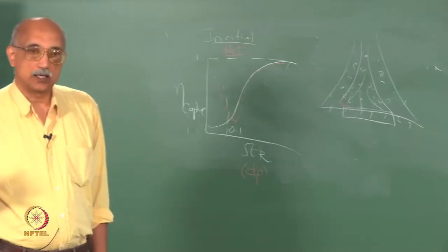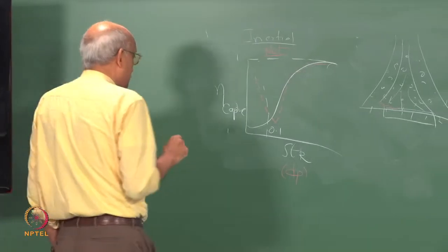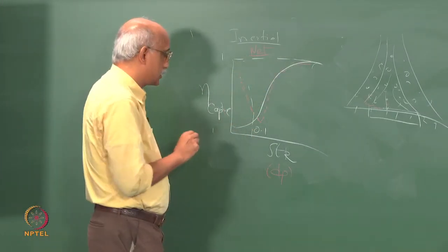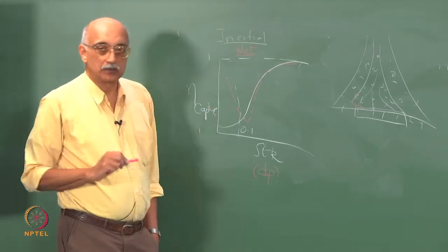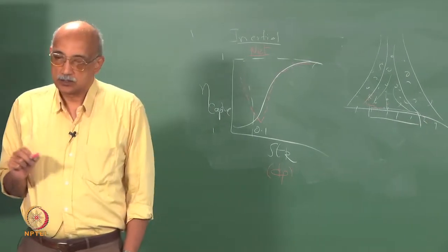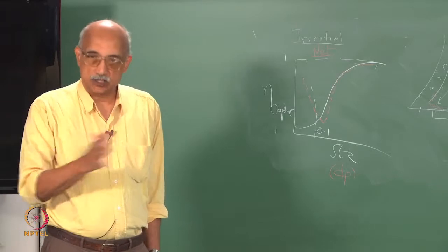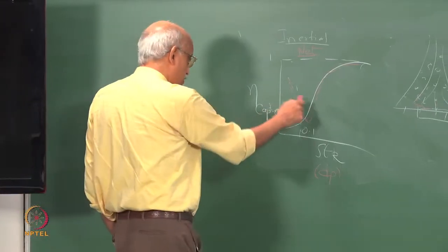So, that again enhances the capture efficiency. The reason for this type of behavior is that at very low particle sizes, diffusion effects become dominant, and since diffusion leads to deviation of particles from streamlines, it increases the capture efficiency.